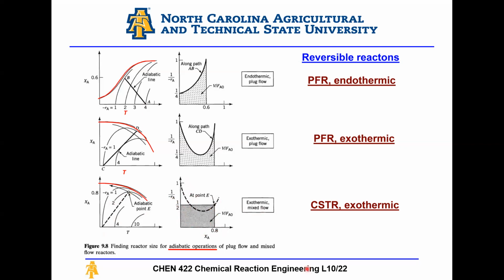Okay, these are just a general idea of how to deal with these systems, or the general approach to design the system. Again, hopefully we can get to the Aspen tutorial covering reactors. Once we get to that point, Aspen can do a lot of these calculations for you. Maybe not to calculate the volume of the reactor, but definitely to get the relationship between conversion, reaction rate, and temperature.